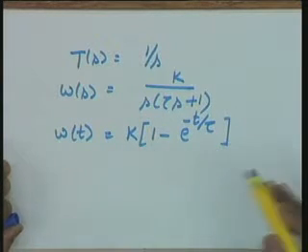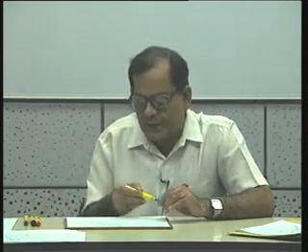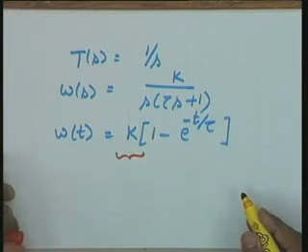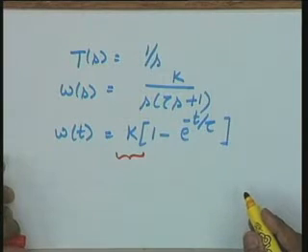So, it means the speed of the system changes to a value k in response to a unit step input, and that is why the name system gain is appropriate for this particular parameter k in the general first order model. It changes the output of the system by k. This is probably the most appropriate reason why the word system gain is used for this particular parameter. Now, let us look at the time tau, that is the time constant tau.